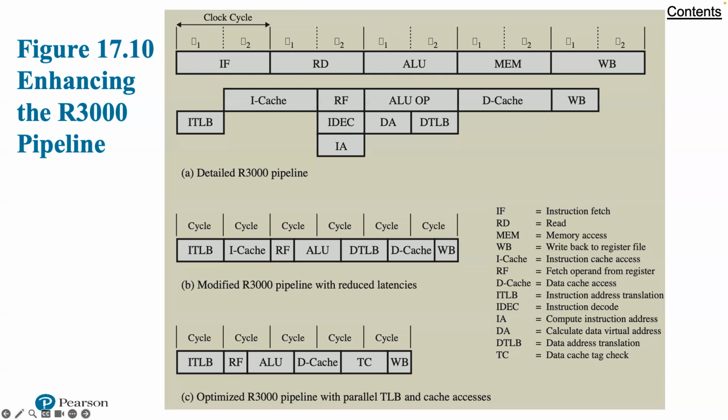Similarly, a load at instruction I fetches data that are immediately used at the op of instruction I+1, while an arithmetic unit / shift result gets passed directly into the instruction I+1 with no delay. This tight coupling between instructions makes for a highly efficient pipeline.